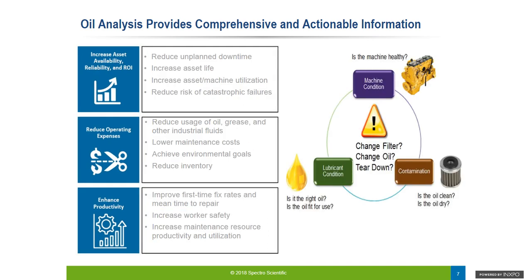In the context of quality data and actionable information, oil analysis traditionally has always had the reputation of providing very comprehensive and insightful information for predictive maintenance. Some go as far as to liken it to the equivalent of a blood test for machinery, where it provides critical information on the contamination, that is the physical constituents, but also the blood chemistry, or the oil chemistry itself.